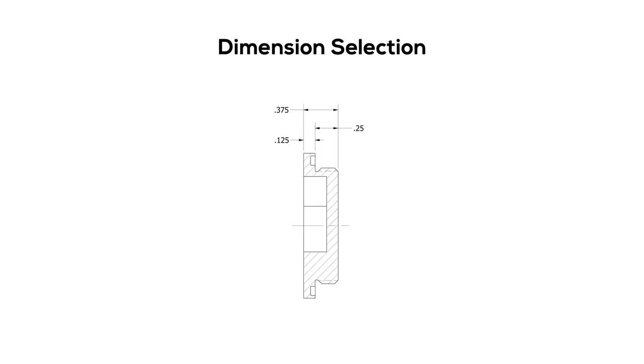For example, this view of the bore cap has an overall length dimension, as well as these dimensions that define the thread length and flange thickness. These dimensions conflict, and one of the three is redundant. To minimize the tolerance stack, it's best to dimension it with these two, but having the overall length is helpful, and we want to show it on the drawing.